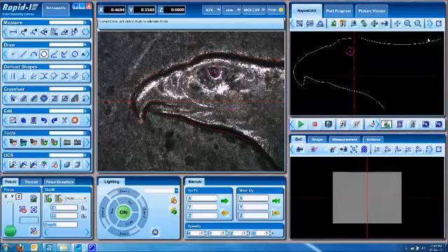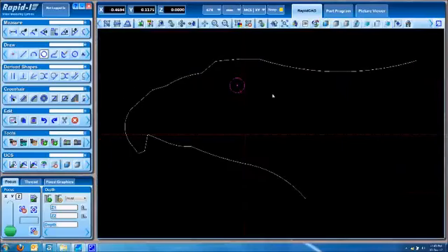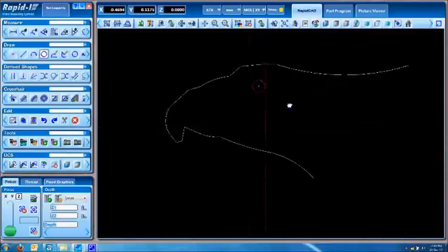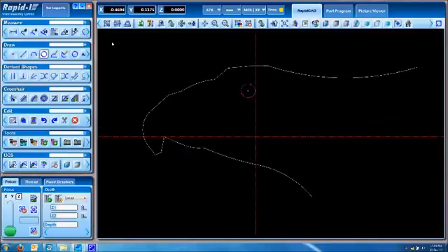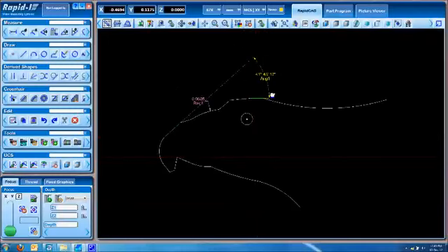Once the drawing is ready, we are now ready to do the measurements. To do the measurements, just maximize the RapidCAD window, and you can zoom and pan just like you can in any CAD software. Switch on the measurement mode, go close to the arc, double click and you get its radius. If you want the angle, click on the line and click on the other line, and it automatically gives you the angle between them. Pretty simple, straightforward and intuitive.